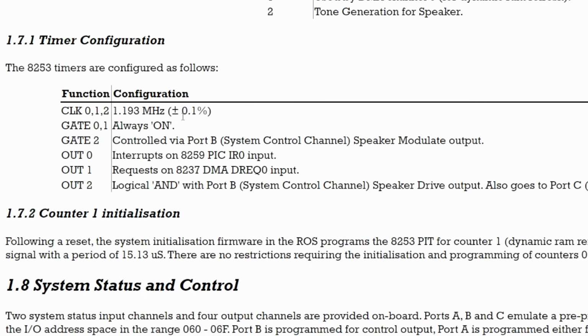So it's actually a fraction of 1/24th of that frequency, and it's not related at all to the CPU frequency. So we know that the CPU and the programmable interval timer are on different crystals, so we're never going to be able to sync those together.